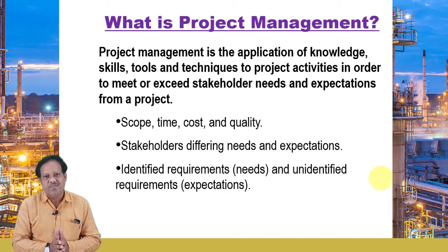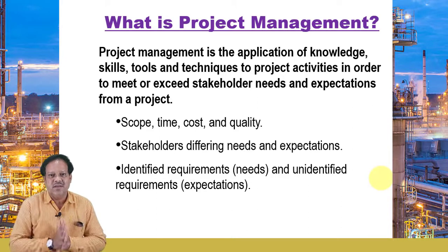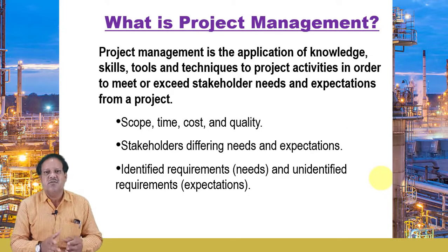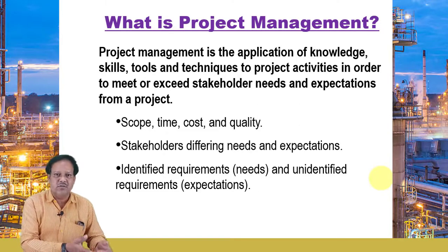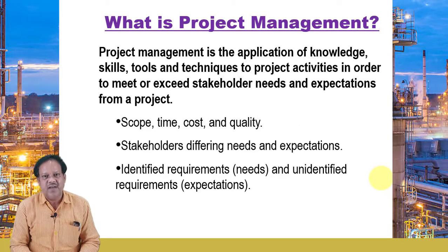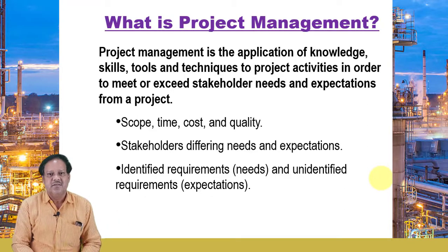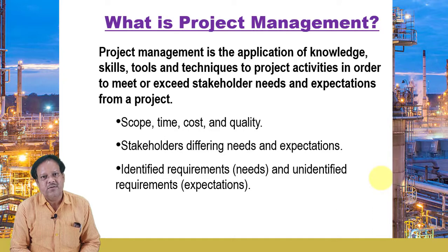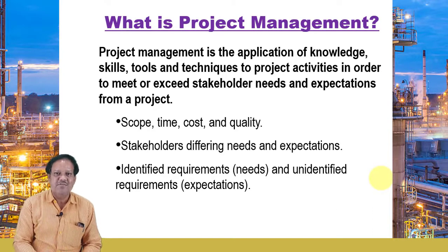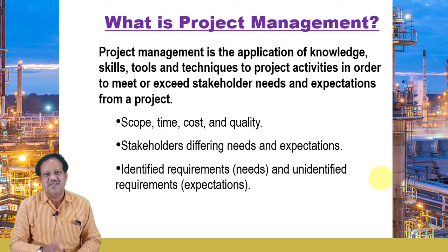Suppose a pump in an industry is going to be installed on a foundation, then you know the primary steps: the pump is lifted and positioned on a particular foundation, aligned and levelled, then pocket grouting is carried out for that foundation, and finally the foundation is concreted. So this is how these skills come into play.